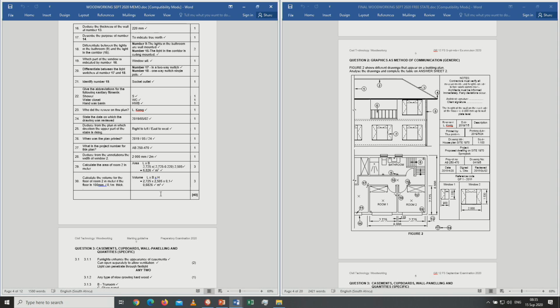So that is the inside to the outside. So on that one, there's a little catch, and that is where you have to minus it with 220. So you take 2725, that is correct, times 2725 minus, comma, 220, the width of the wall. That will give you 2,505.